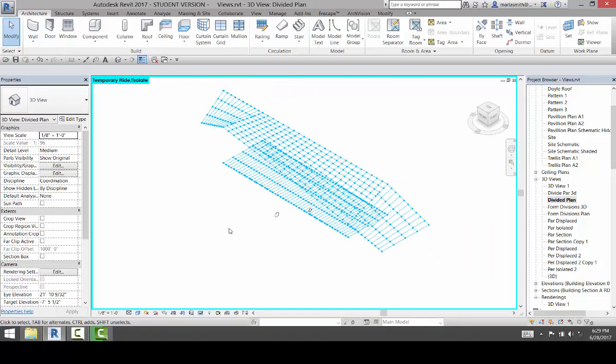So what I'm going to do now is turn on my section box over here. So I'm going to click it on. And I can't see it because it's actually hidden. So it's a little annoying. So I'm going to come down, and there's two different ways to hide things. We did the isolate element here with the glasses, but there's also the being able to right click and hide element. And that is controlled by the reveal hidden elements.